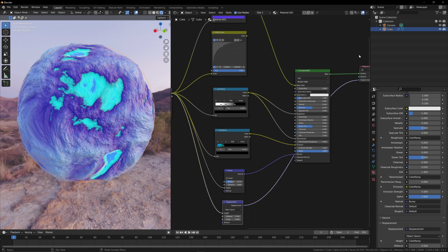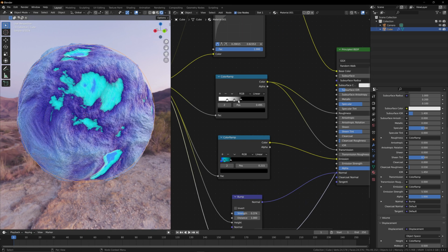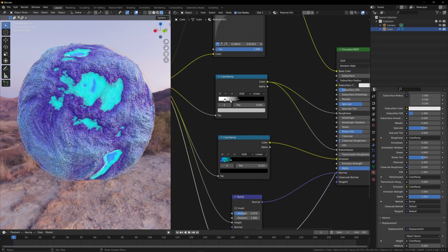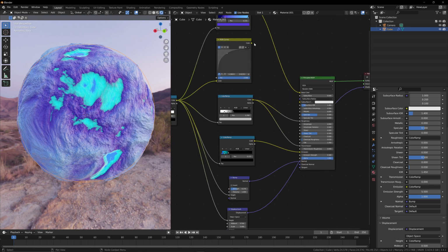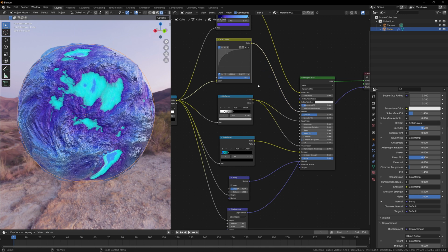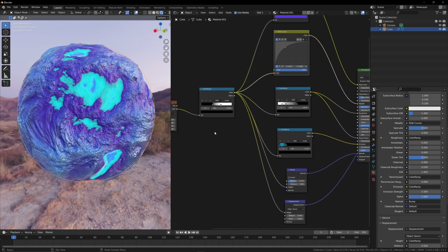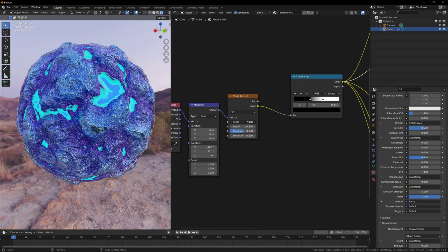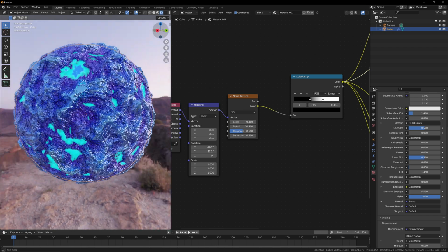And that is about it at this point, I think. We can go back into this and really tweak this with the roughness values here, for example. We could bring this down, make this a bit shinier. We can reconnect our metallic output here to make this feel more metallic again. And then we can go here and look at our scale and other detail settings for this as well. So if I increase the scale, this is going to start to look bumpier. I'm going to start to get a different look to this as well.